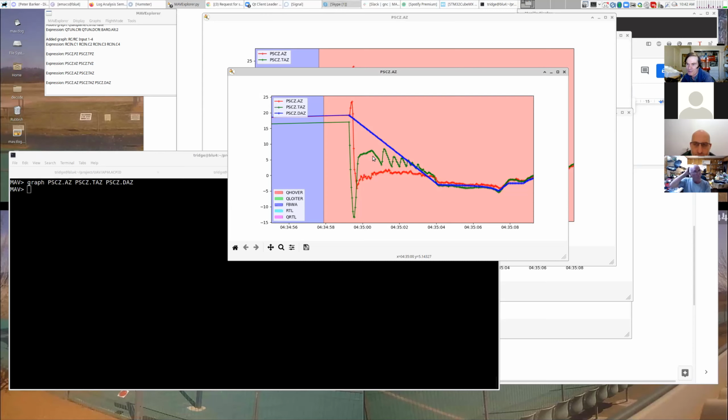And it's very high throttle and pushing the aircraft up. Okay, now it can't actually achieve this acceleration. It can't maintain 1G vertical acceleration or 2G initially, right? It just doesn't have enough throttle to do that, but it's trying to do as much as it can to do what it was told to do. So the bug in this code is this initialization point.